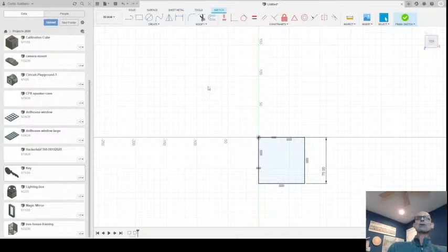All right, something else I want to point out is that this was a dimensioning tool that we used here, and we manually typed in 75 millimeters. But there's a way that we can create parameters or modify variables that we can then represent these values in, so that we can copy this information elsewhere. Here, if I go to modify and choose change parameters.